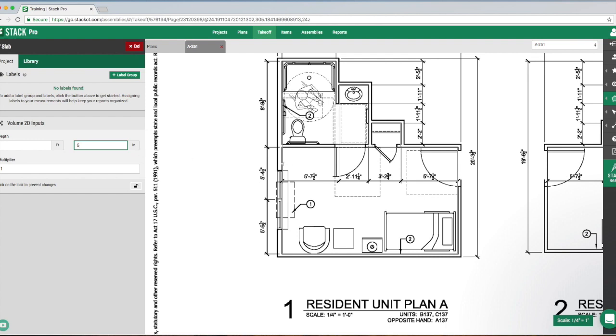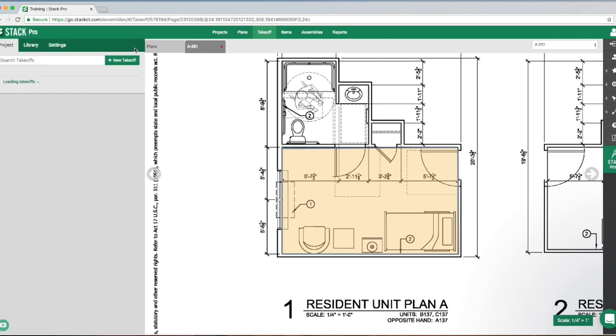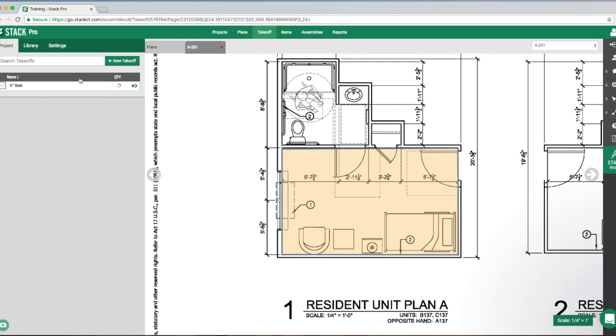So the way our drawing tools work, we're going to do one click, and then I'm just going to pull the mouse over. I'm going to do a click on every turn, work my way around, and then I'm going to double click right there. And that's going to shade that area in for us. If I click end, that'll show you what we've done so far. So over here on the actual takeoff template, it's going to give us a running total for the project, okay? And this is, again, a small little area. So it's showing that we've got 4 cubic yards.